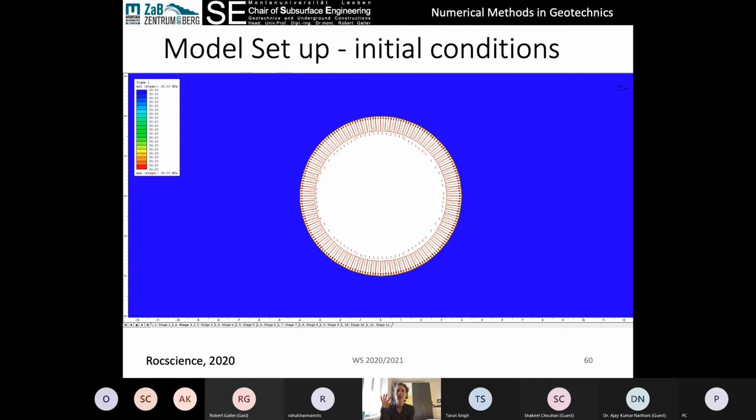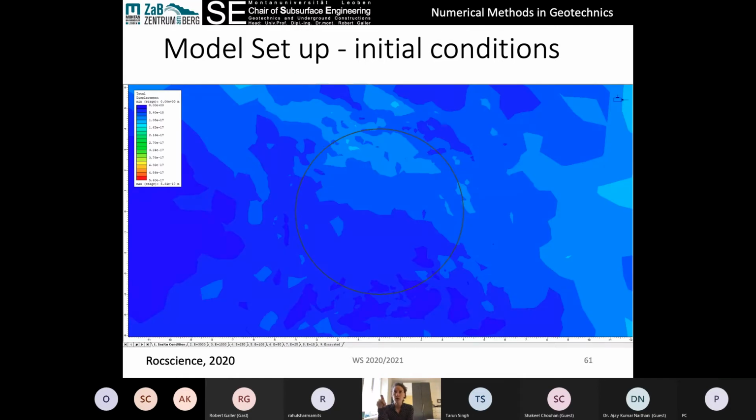We have to put in the most appropriate stresses, and then we have to run the model. The model must be initialized to allow all of the minute deformations to occur, especially if we're using gravity, to allow the model to compute the gravitational stresses and allow any movement. We visualize it as movement.